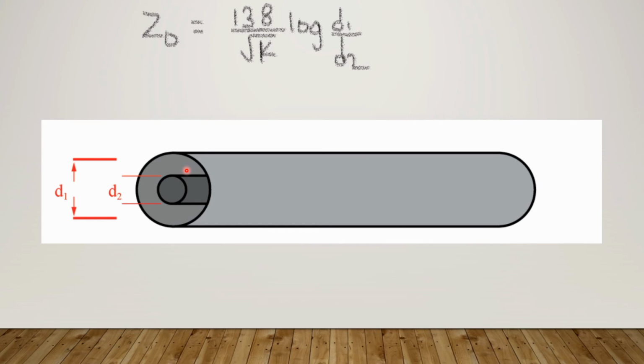We have found the characteristic impedance, and the second one is propagation speed, that is the velocity of propagation. Whenever there is a to-and-fro transfer of motion due to these electric charges, they travel at the speed of light. This generates the velocity of wave propagation. We can calculate it using the formula v = c/√k, where c is the velocity of light and k, as I said earlier, is the relative permittivity of insulation between conducting wires.